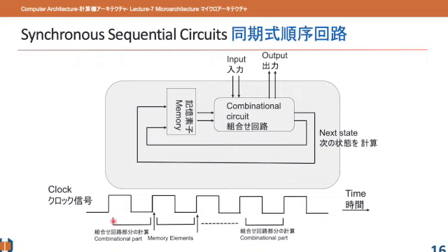Well, so it's detailed in every clock cycle. If you consider from the rising edge of a cycle to the next, this is a combinational part. So within this period, one thing is executed by the combinational part. And then the memory element stores the result, and at the next rising edge the combinational circuit executes the same thing, having the memory input and the current input to find the output. So this is the sequence: it comes from here, and then restores the memory.